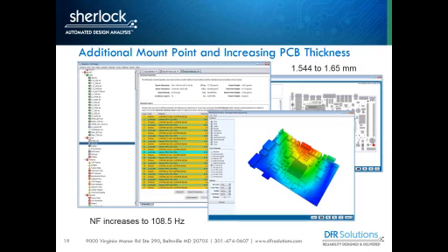But as you think about it, it's a really competing mechanism. As I make the board thicker, the stiffness of that board increases dramatically because it's based on the moment of inertia of the board, but I also have to fight against the additional mass of the board. But mass only increases linearly. Stiffness increases as a power law by the moment of inertia.